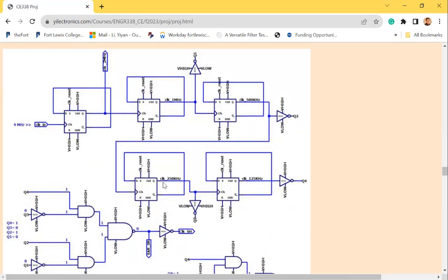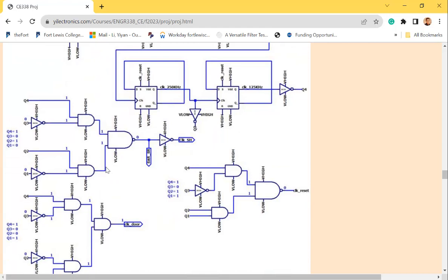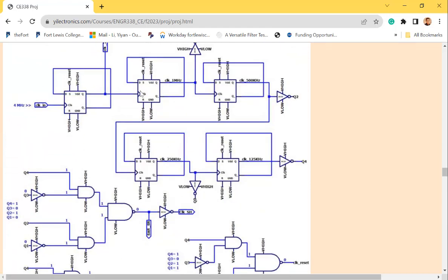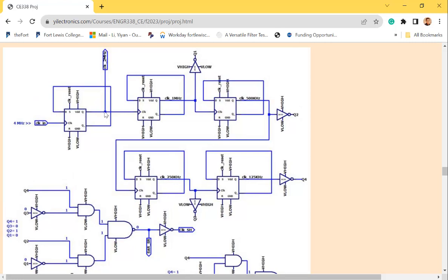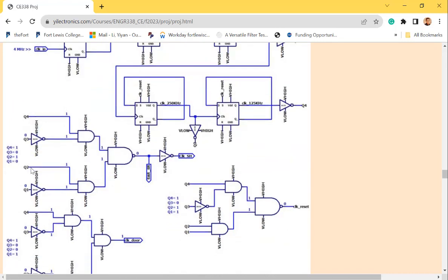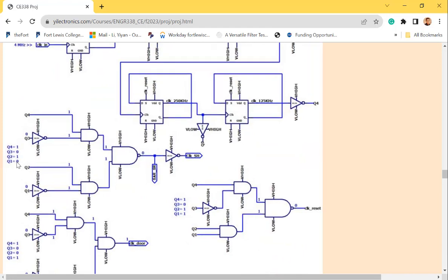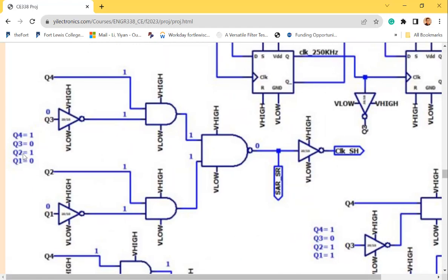So for example, this one, okay? So this is a regular counter circuit. It has the original clock. Count from 0 to 1, 2, 3, 4, 5, 6, 7, 8, whatever. So it's just a regular counter counting one by one each time, and outputs Q1, Q2, Q3, Q4, okay? And if I want this counter to count until 1010, what is 1010? 10. If I want it to count until 10 and reset it,